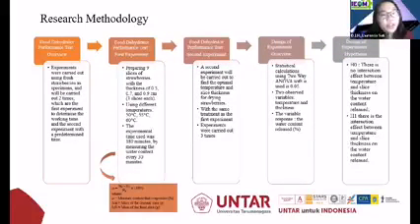Then we go to the food dehydrator performance test, where there are 2 experiments. The first experiment is by preparing 9 slices of strawberries with thicknesses of 0.5, 0.7, and 0.9 centimeters, using different temperatures according to the manual book: 50, 55, and 60 degrees Celsius. Then the experimental time used was 180 minutes, measuring the water content every 30 minutes by the formula below.